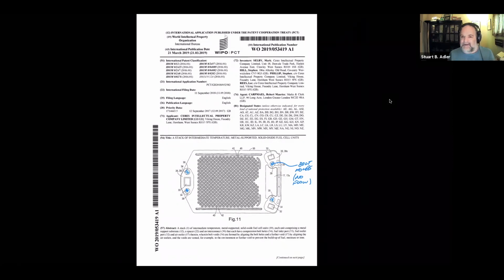So once you send fuel into a manifold or you're pulling air out of a manifold, you can't control the individual flow to every cell. So you need to design this with the appropriate space between the interconnect and the plate and the size of the manifold holes so that the pressure drops in this whole thing are balanced. So at the bottom, you've got a fuel inlet and you've got the exhaust outlet. The cell that's closest to that manifold feels the biggest pressure drop.